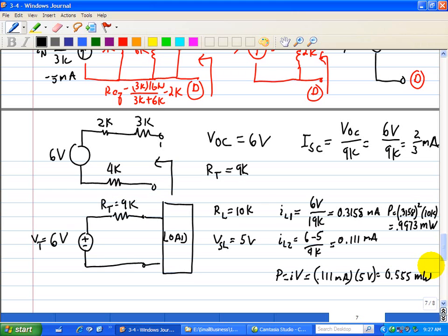A typical example of this situation is a battery charger. Just a comment that the Thevenin equivalent allows us to calculate the power delivered to the load, but it does not tell what power is dissipated in the source circuit. In other words, the Thevenin equivalent circuit has the same IV characteristics at the interface, but it does not duplicate the internal characteristics of the source circuit.